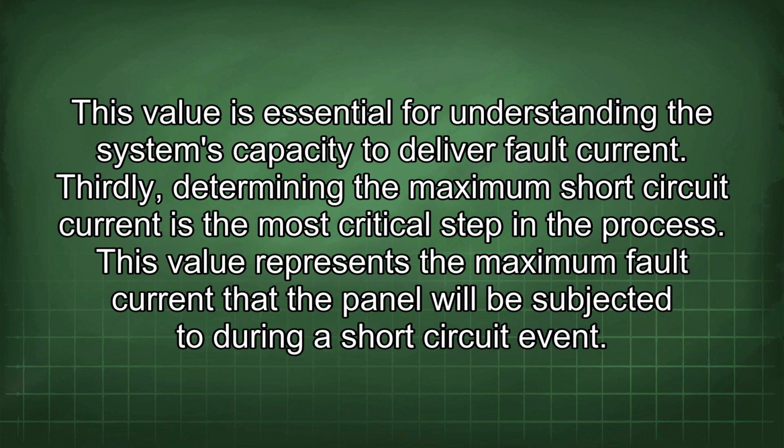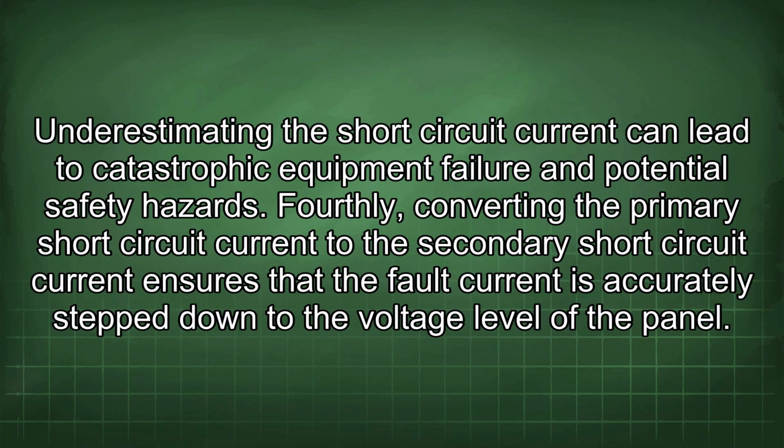Thirdly, determining the maximum short circuit current is the most critical step in the process. This value represents the maximum fault current that the panel will be subjected to during a short circuit event. Underestimating the short circuit current can lead to catastrophic equipment failure and potential safety hazards.